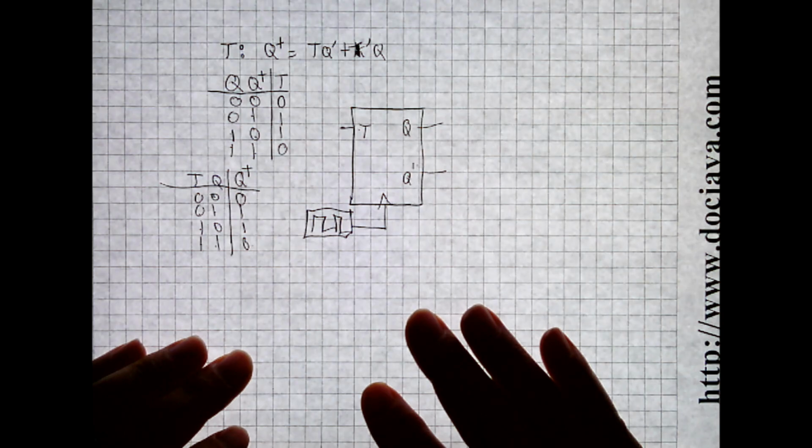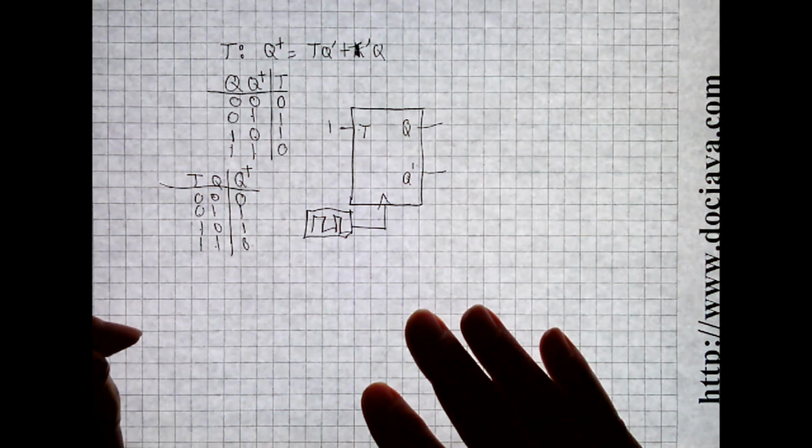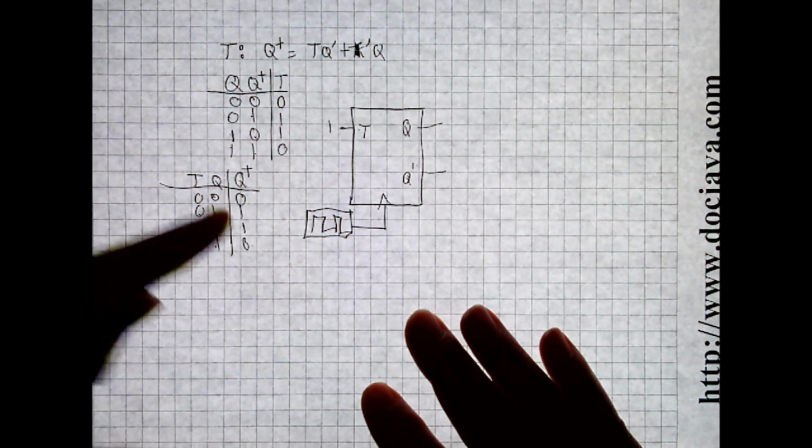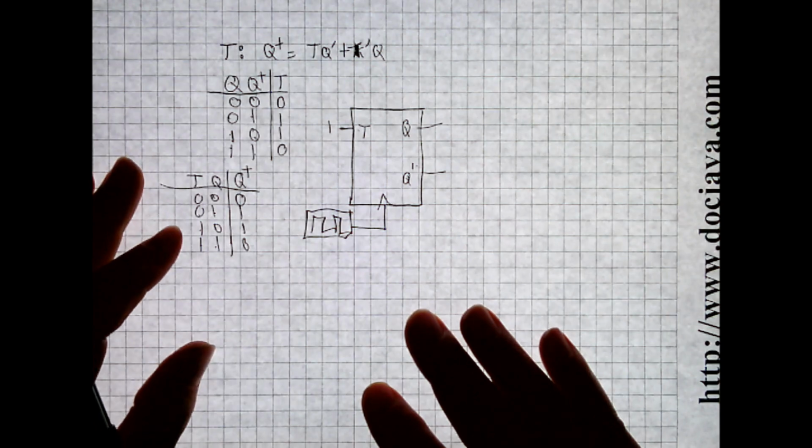It'll change from 0 to 1 or 1 to 0. So, in fact, if you just put a 1 in there and leave it there, you made a buzzer. It will just keep changing state and go bzzz as fast as it can.